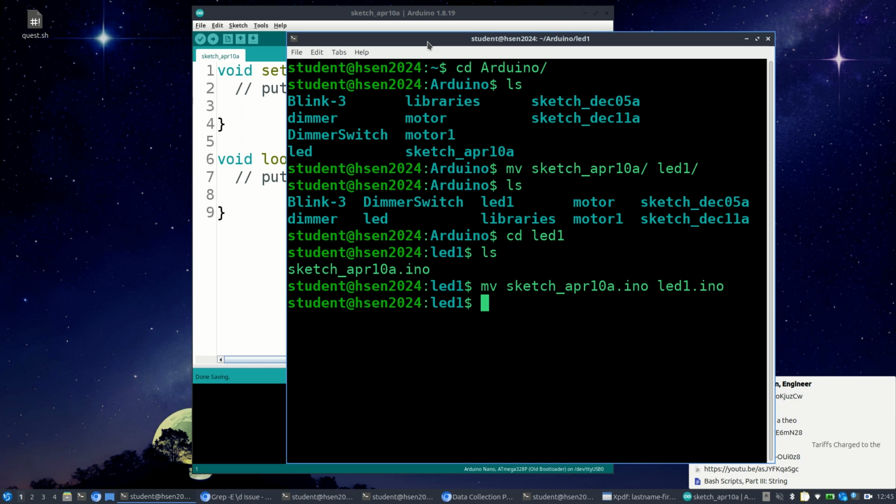So let's go in now. Actually, it might be a good thing for you guys to take your Arduino and mount it on the board. Okay, if you recall how to do this, you want to set it up so that the end that's got the port for the USB, the mini USB cable, is at one end, okay? And you want to mount it so that it straddles the non-conducting channel, right? Remember how to do this? You put the connector point up here.